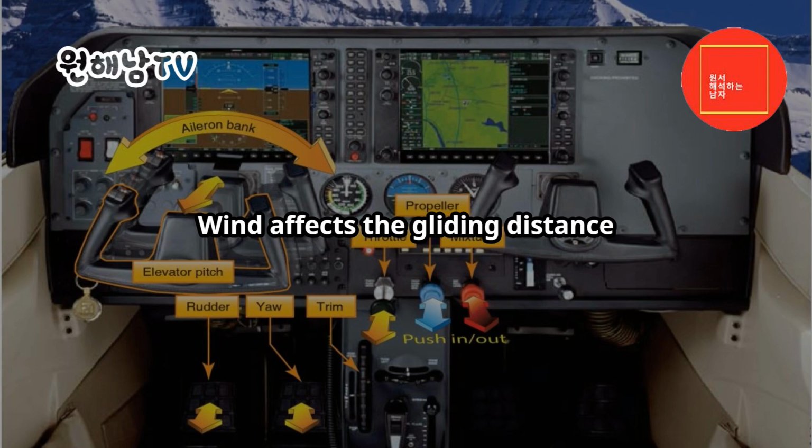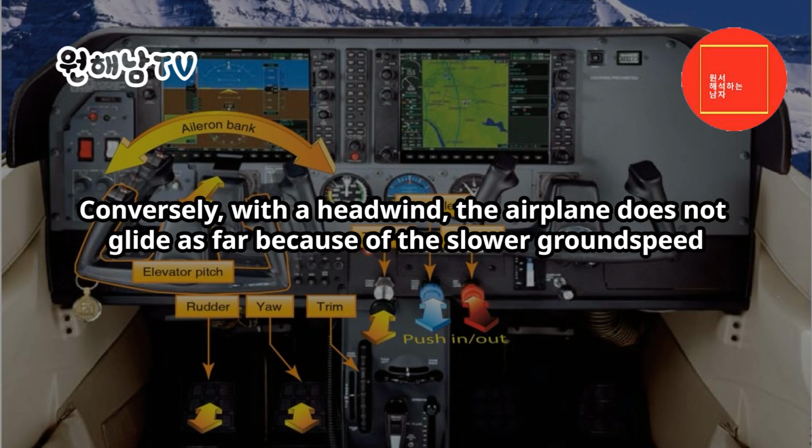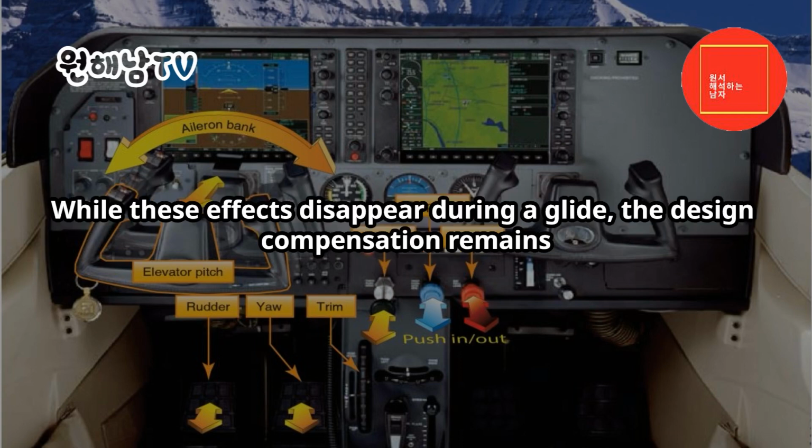Wind affects the gliding distance. With a tailwind, the airplane glides farther because of the higher ground speed. Conversely, with a headwind, the airplane does not glide as far because of the slower ground speed. This is important for a pilot to understand and manage when dealing with engine-related emergencies and any subsequent forced landing. During powered operations, the airplane design compensates for the effects of P-factor and propeller slipstream. While these effects disappear during a glide, the design compensation remains.